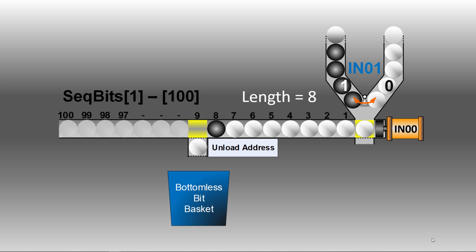So every time you create a Boolean data type, you are using a 32-bit word. Now in Micro 800, you don't really have the opportunity to shift bits around in a data type like a dint or an integer or an unsigned integer, single integer.